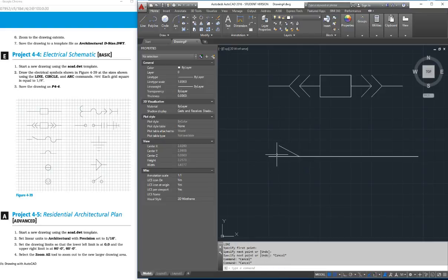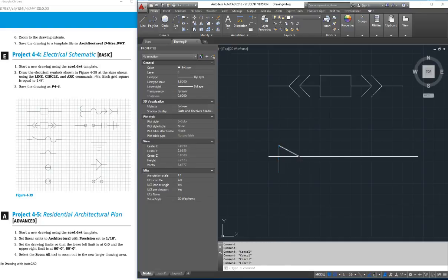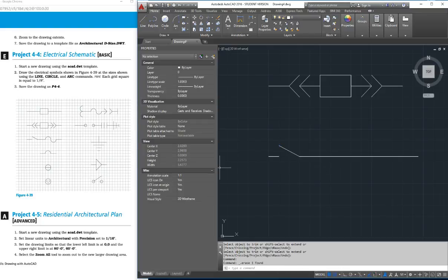Okay, so this is a little bit of a problem now. A lot of times we need to draw extra lines that we just end up deleting called construction lines. So what I'm going to do is draw a line from here down, and it doesn't matter how far down because I don't need this bit of line right here, but I need this and I need this. So once I draw this line down, I've created 2 points, an intersection here and an intersection here. So what that's going to let me do is do a trim, enter, click, and that goes away, and then click and hit the delete key, and that goes away. What do we got here? 3 grid squares. So I'm going to go 1, 2, 3.